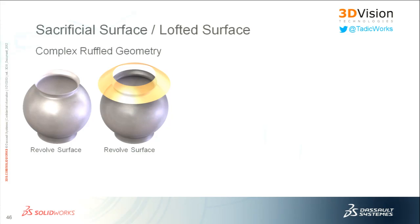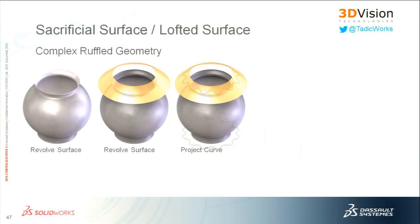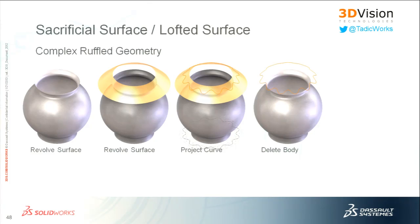Again, it's a sacrificial surface that I want to reference. What I could draw was a ruffle shape, the wavy shape down at the bottom on a 2D plane. That's really simple. I just draw one and then do a sketch pattern all the way around. But then I could project that wave up onto that conical surface with the project curve. It's another curve tool. And that generated the geometry that I was looking for, or that edge.